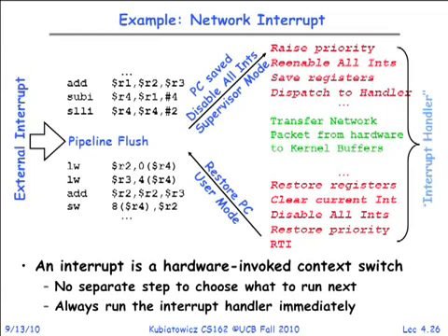In the previous slide, you mentioned software interrupts. Can you explain what you mean by that? So a software interrupt is basically the same process but invoked by software. Sometimes there are even bits in the hardware interrupt controller that you can set that, when you get into the right mode, will actually cause the same sort of interrupt and return, but it's invoked by software rather than an external hardware event. Does that apply to a separate thread of execution, like sending interrupts, or if you only have one thread, can you use it?